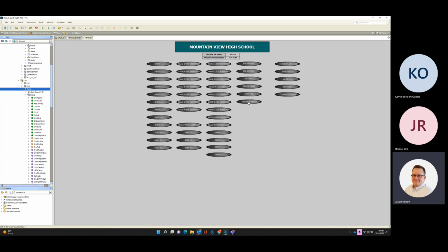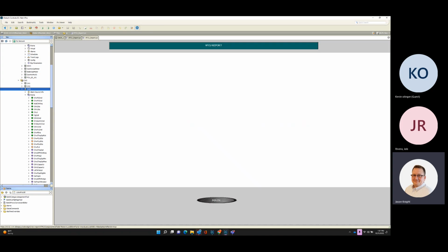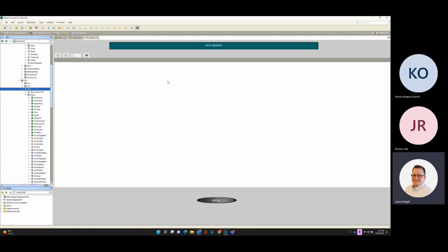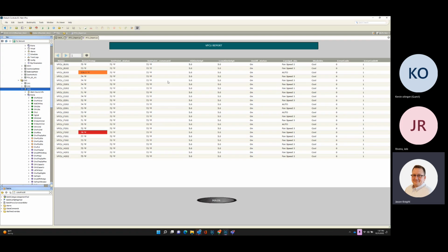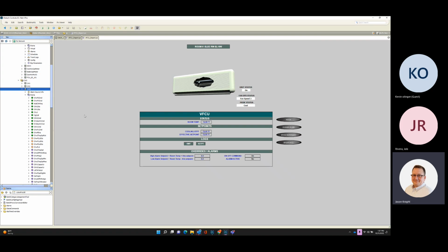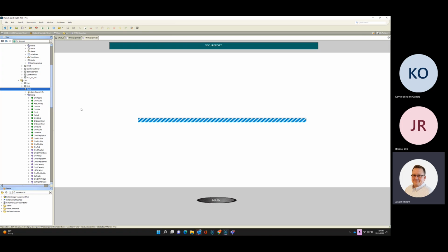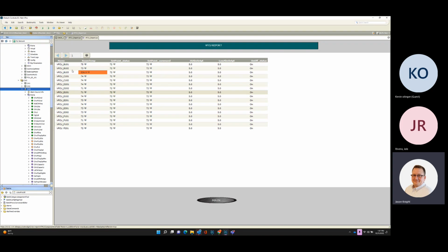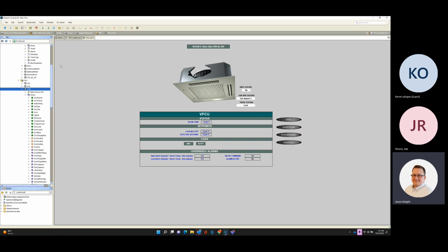And then the one thing I wanted to leave you guys with was this VFCU summary. They're those Daikin standalone IDF rooms we had started talking about, and we kind of went on to different subjects, but I just want to bring these up real quick. These are all the IDF room temps. We left off, you click on the hyperlink, it takes you to the wall cassette. I did 2 different graphics for this. Some are cassettes, like the square cassettes in the middle of the ceilings, and others are wall modules. So I did 2 different graphics to represent what you were dealing with for those 2 rooms.